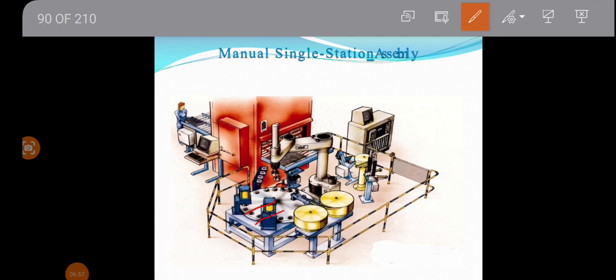In this plate, we arrange a number of slots. Each slot is used for assembling the product, with one operation after another in sequence. For example, take a Geneva plate with a number of slots, which may be 6, 8 or 12 slots based on our requirement.